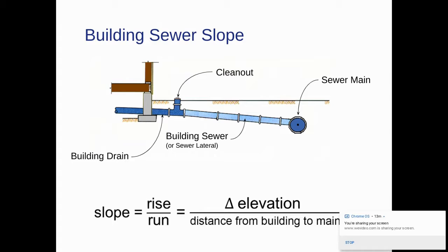You have them spaced every 25 to 50 feet for smaller pipes, and larger ones in your mains outside. That's what you see with the manhole covers. Those are essentially large cleanouts so that a person can get down in there and put tools down through the pipes into the next manhole and try to clean them out if a break or a clog happens.